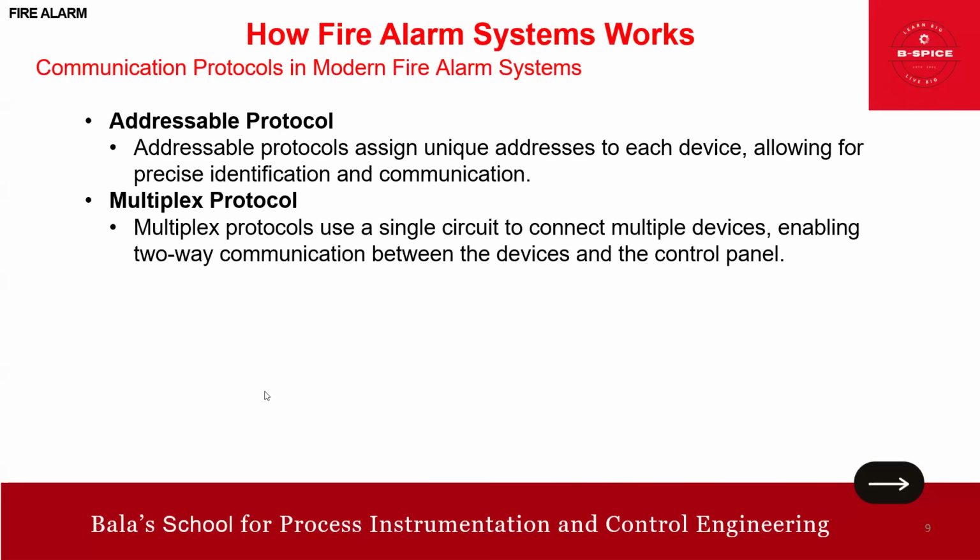Addressable protocol. Addressable protocol assigns a unique address to each device, allowing precise identification and communication. Then multiplex protocol. Multiplex protocol uses a single circuit to connect multiple devices, enabling two-way communication between the devices and control panel. So analog, digital, addressable, multiplex. These are the protocols.